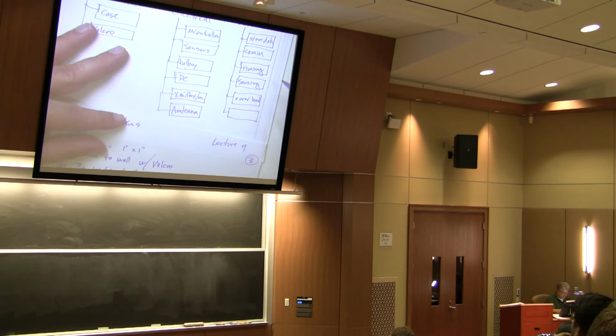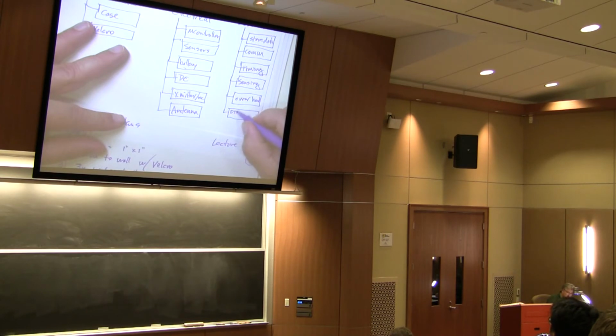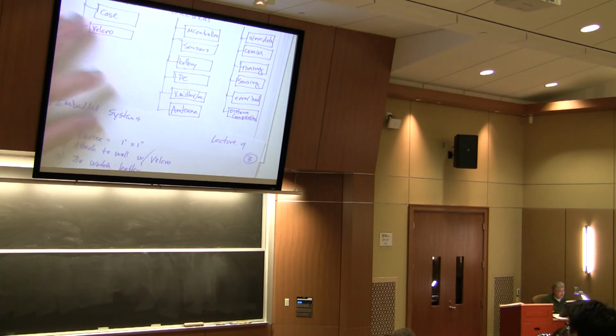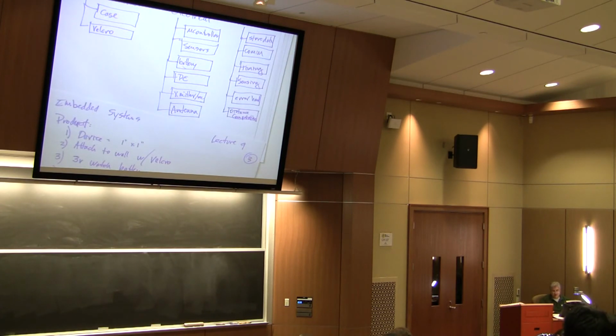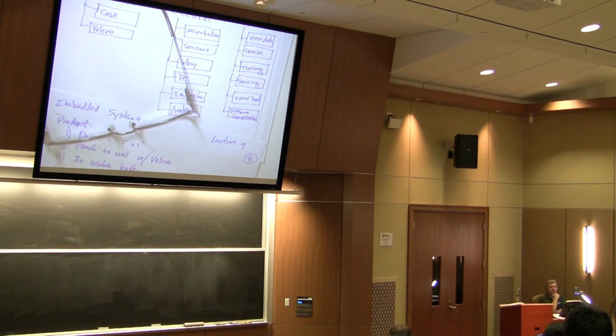And probably one big one that everybody's missed so far: computation, actually. All right, the distance computation. And even though it's not in here, it is implied that there's going to be overall operating system control. But to be honest with you, for something this simple, you probably don't need a full-blown operating system. You can get by with what we call a roll your own, or really just a super loop. In other words, just do a few things and go on.